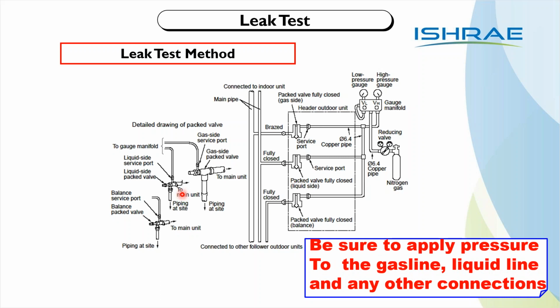Now, if you still have further doubts, there are two ways of giving nitrogen pressure. One is you can give to copper pipe separately. You can isolate the indoor unit separately and give pressure for the indoor unit separately. However, outdoor unit will have refrigerant pressure, but make sure when you open the outdoor valve, if it is showing 0 psi, please do nitrogen test.